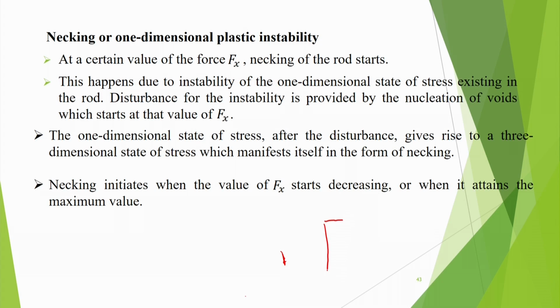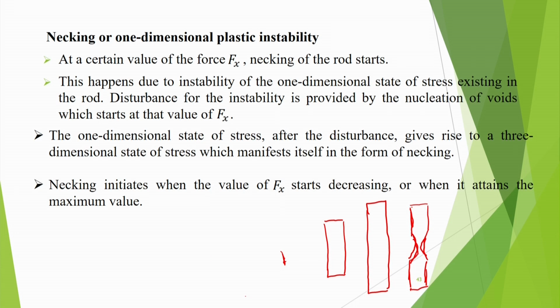Suppose this is a material and it is elongating. It got elongated here, right? But if the necking has started, the material may start forming a neck type of thing here. That means here the material will deform, the state of stress becomes triaxial, and ultimately it will lead to the fracture. So, the necking phenomenon occurs due to this.